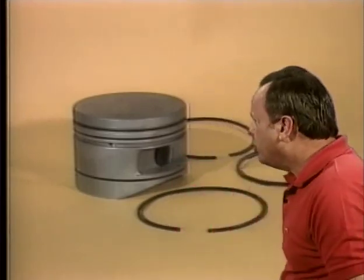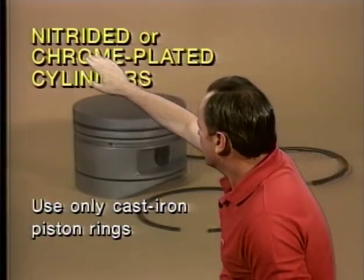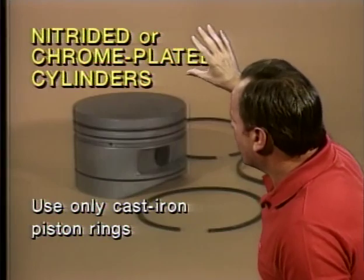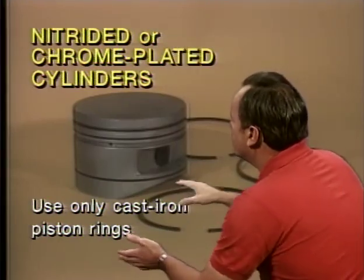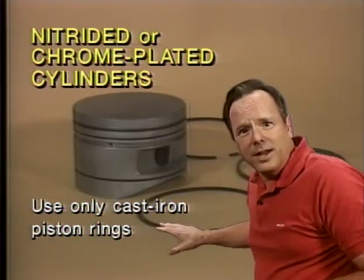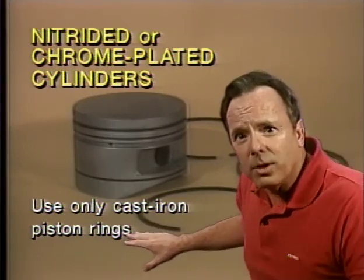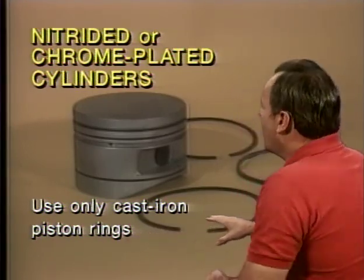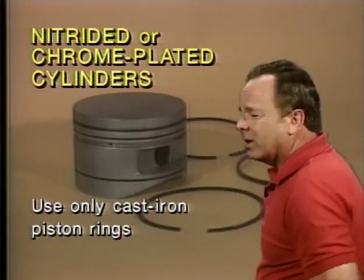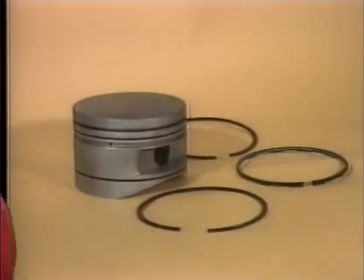So if you do have, we'll say, a cylinder that is either nitrided or chrome plated, these are hardened cylinders, then you would only want to use cast iron piston rings. On the other hand, if you have a plain steel cylinder, you could then use chrome plated rings. But the important thing you want to know is never use a hardened ring on a hardened cylinder or you could wear that sucker out in nothing flat. All right, now let's talk about the tolerances allowed in aircraft cylinders.